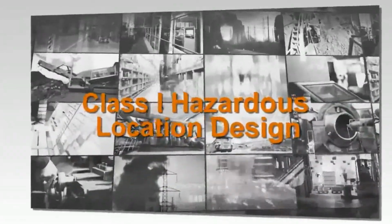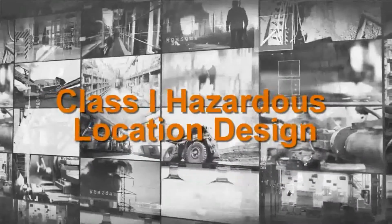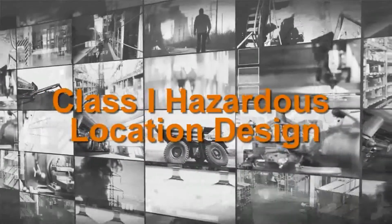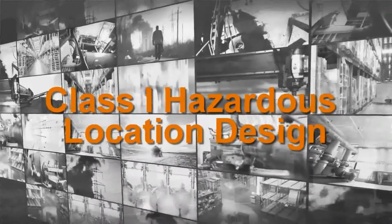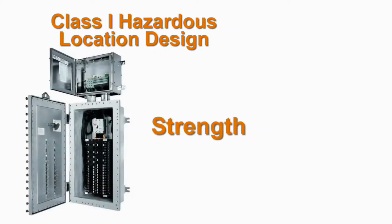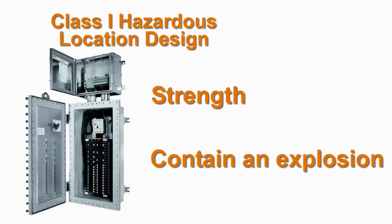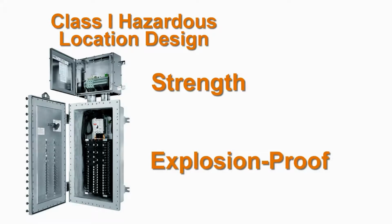Now let's get down to the specific hardware and how it is designed and constructed to be suitable for hazardous locations, starting with those designed for Class 1, gas or vapor applications. The first requirement for a Class 1 enclosure is strength. The enclosure must be strong enough to contain the explosion within, and the walls must be thick enough to withstand the internal strain. It also has to be explosion-proof in case gas or vapors get inside.